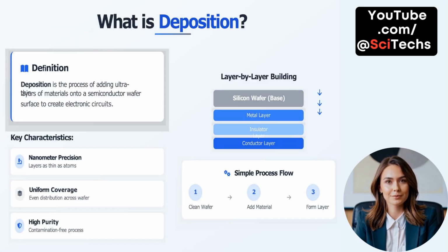What is deposition? Deposition is the process of adding ultra-thin layers of materials onto the surface of a semiconductor wafer to construct electronic circuits. These layers can be conductors, insulators, or semiconductors, depending on the design requirements. The building happens layer by layer, starting with a clean silicon wafer as the base. Materials such as metals, insulators, and conductive films are then deposited in a highly controlled sequence. The goal is to achieve nanometer precision, meaning layers that are only a few atoms thick.